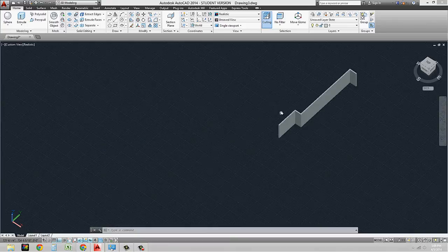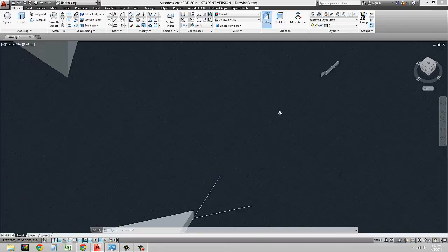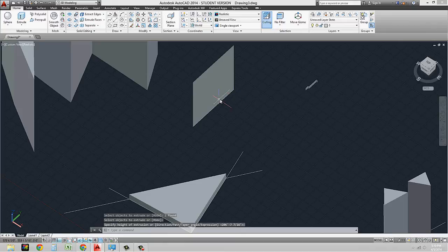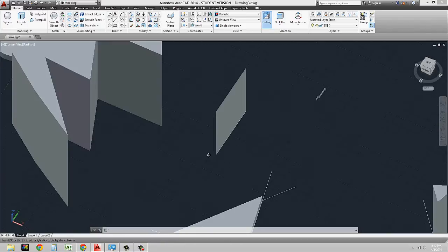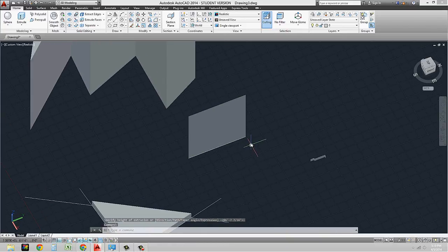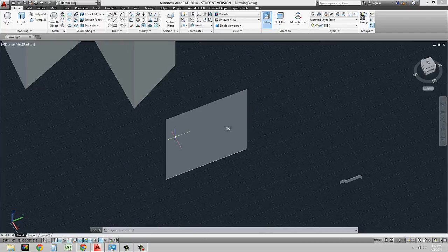Now the one thing that I wanted to warn about is if I have a line, technically yes, I can click on it and I can extrude it, but this is not 3D modeling, this is a very bad way of 3D modeling, because if I do that, it doesn't really treat a line as an extruded solid, and that's what we want with every 3D program that we work with. When we extrude planes like this, and this is actually how SketchUp works, we don't really have a thickness to our model, and you'll see down the road that it'll start to affect it.